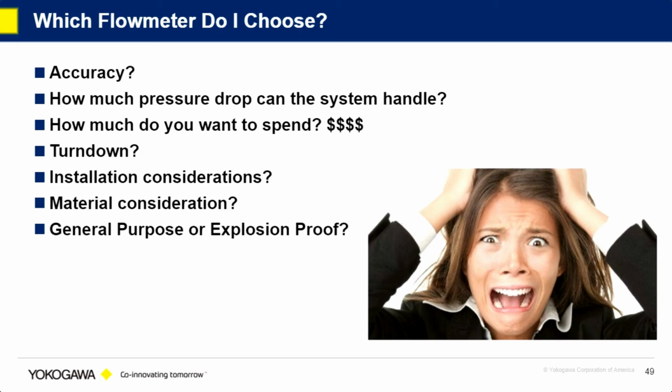But financially, if you need a high accuracy measurement, mass flow, and you can use a density measurement, then that's where we're going to go towards a Coriolis meter.